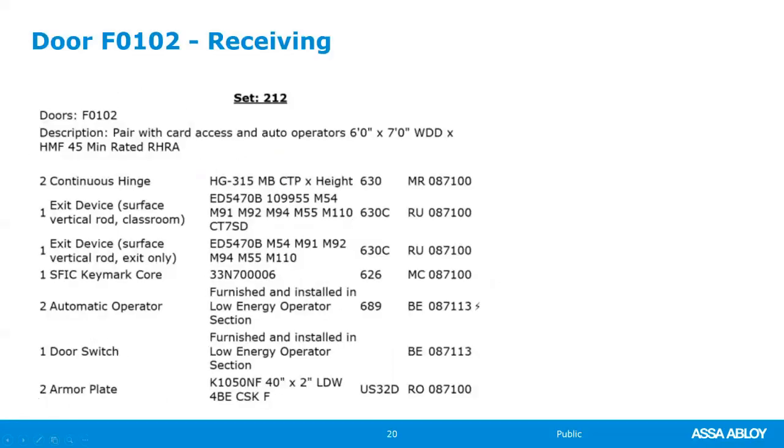The other reason is this is a wood door. The other one was a metal door. And I wouldn't put concealed vertical rod in a wood door that gets any kind of high use. And this is a fire rated wood door, so it would have the 5-inch wraparound metal channels on the meeting stiles. It would look awful. The door itself wouldn't be as heavy duty as the hardware, and there would be problems. We don't want to have any problems in a hospital.